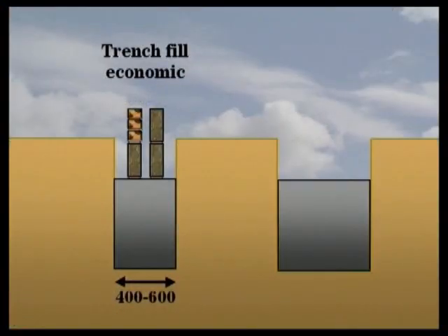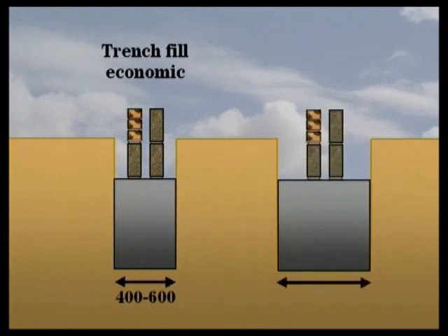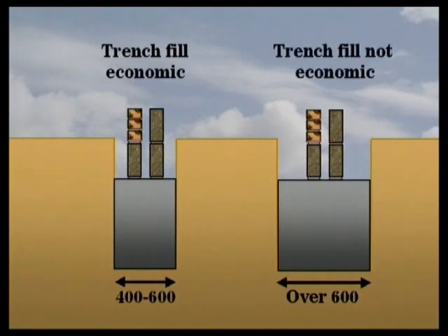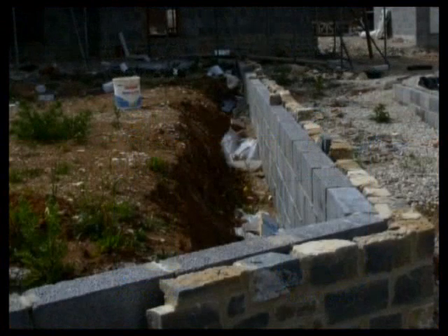Where foundations have to be wider than 600 millimetres because of the bearing capacity of the ground, trench fill may become too expensive. It's often cheaper to provide traditional strip foundations.